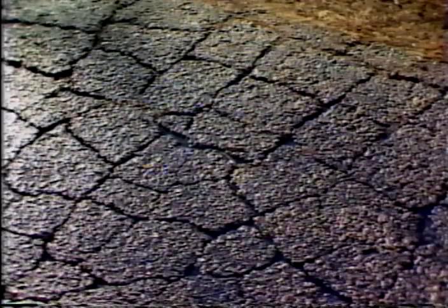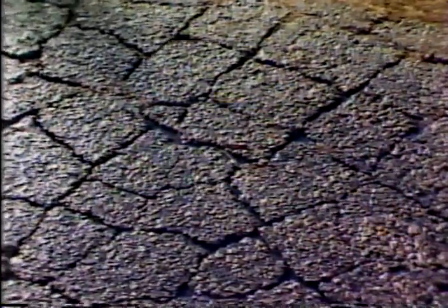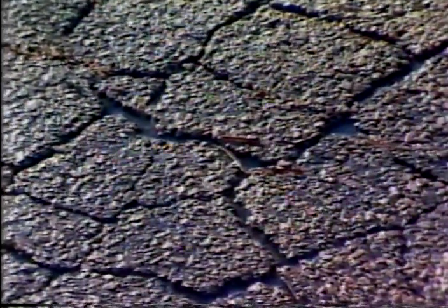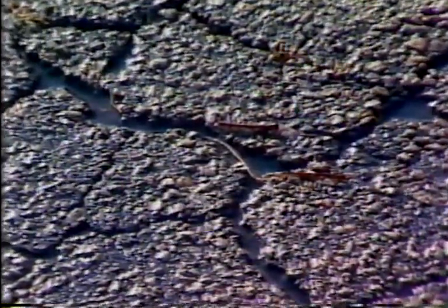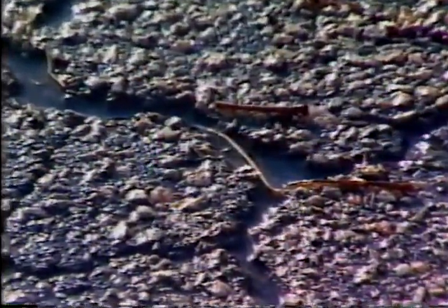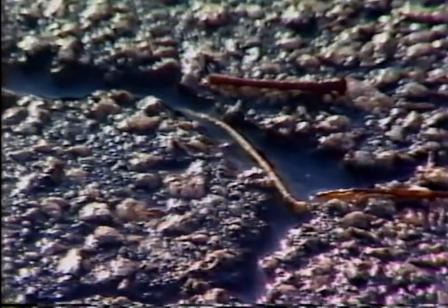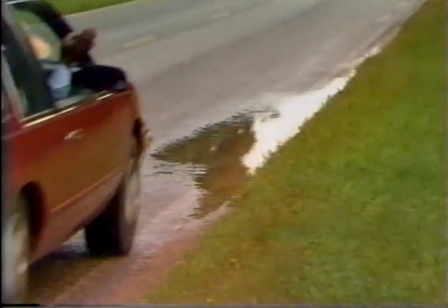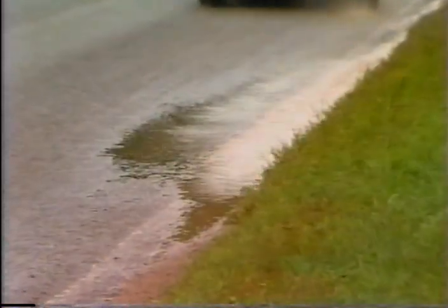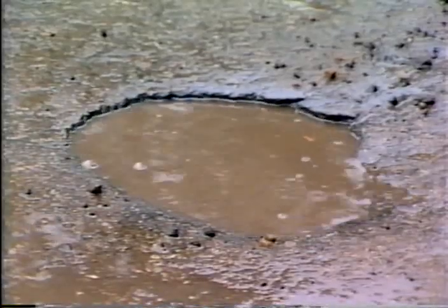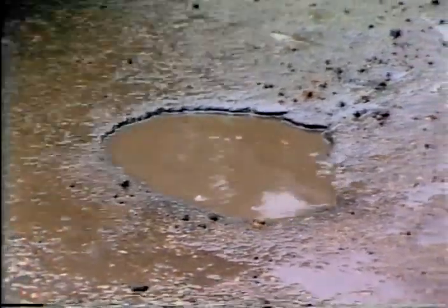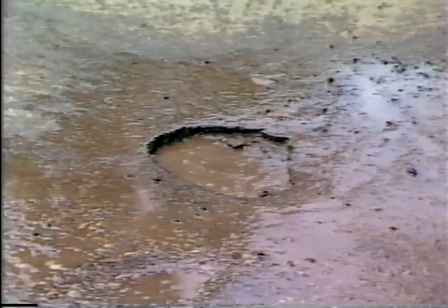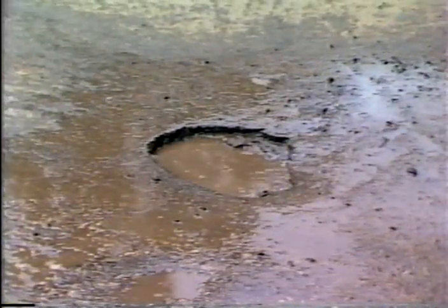When water enters the base of the pavement, it weakens the pavement and reduces its ability to carry traffic. Water reaches the base materials either by intrusion through cracks in the pavement surface, or standing water may seep into the base from the shoulder area where there is poor drainage. Combine the weakened base condition due to water with traffic, and potholes occur. The need now is to repair the pothole.